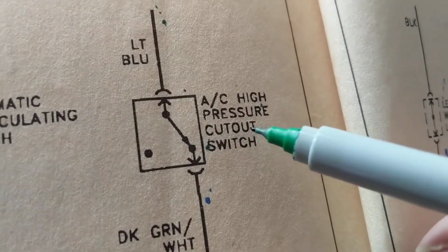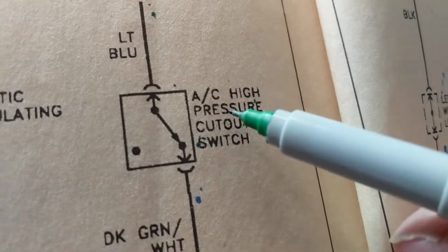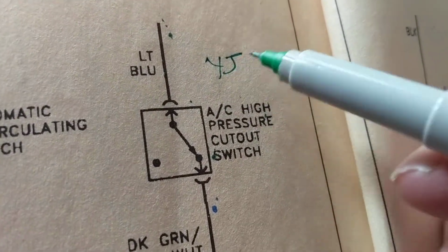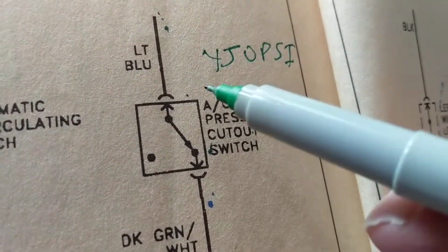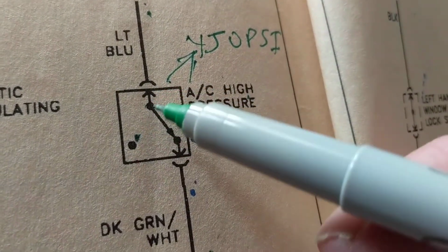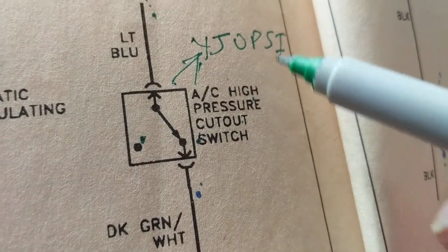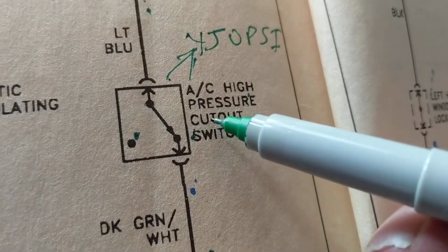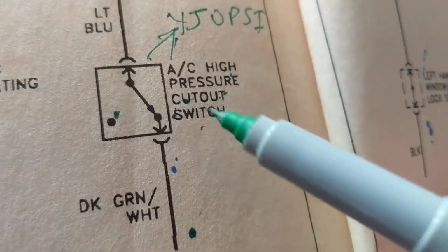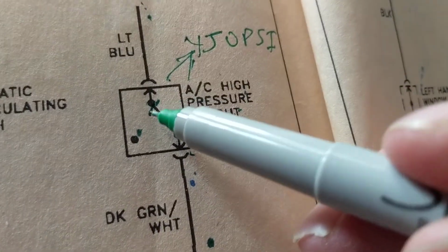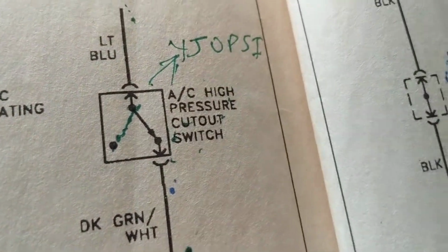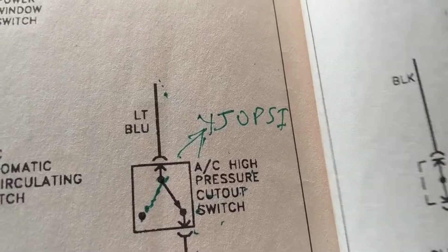And with that hint that I just told you, guess what this does? If this pressure is more, let's say, than 450 psi, guess what he's going to do? He's going to open the circuit. Once he opens the electrical part of it, the compressor doesn't work. That's why cut out is a hint to tell you it cuts off. But not in this position. In this position, it'll open this way. That's that. Now, let's go for another one.